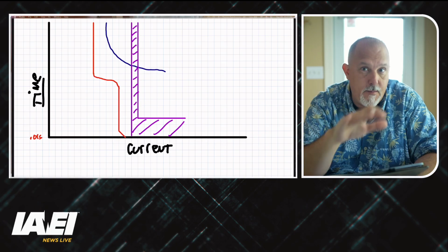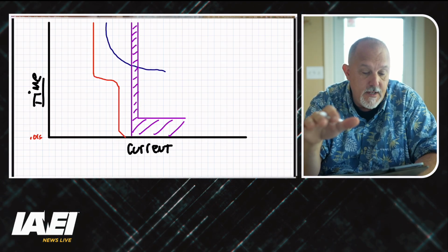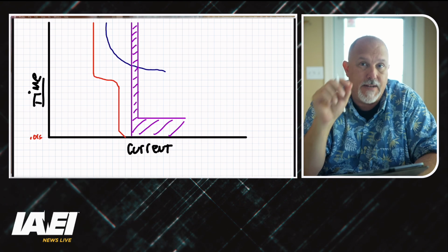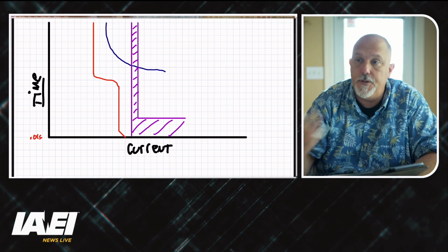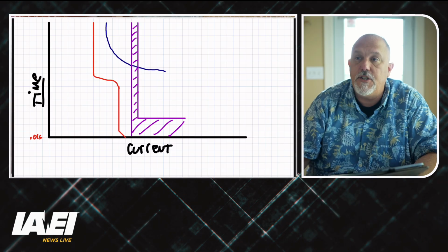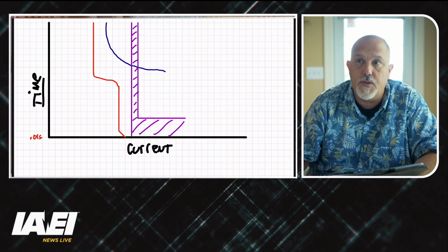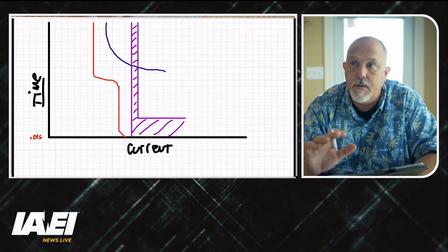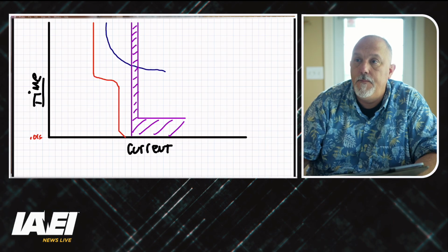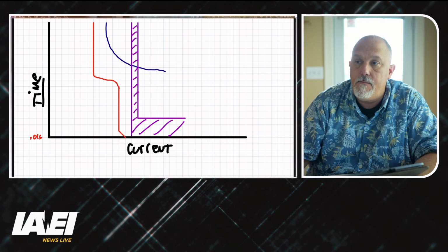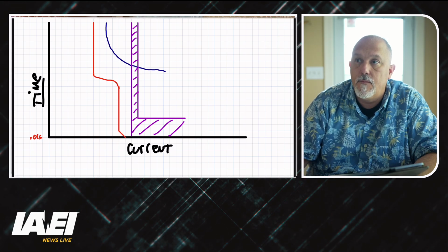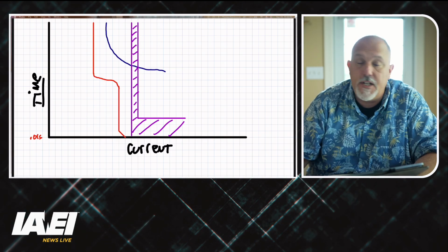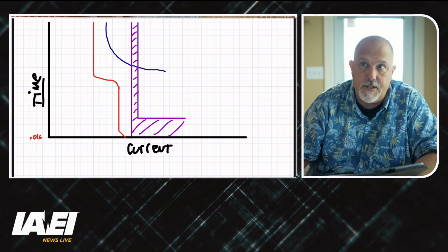This is her process. Now remember, we haven't picked a conductor yet. So she goes straight to providing and selecting the overcurrent protective devices for this load. And then she selects the overload, and then she selects the short circuit, and sometimes overload and short circuit are all in the same device. And then she does ground fault protection as well. And then finally she goes to the conductor ampacity calculation.